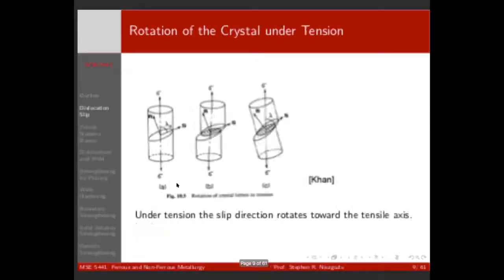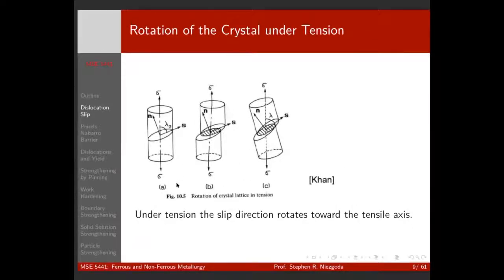So you may have seen this; it'll come up in the reading, but single crystals: if I cause slip here on this plane, and I have this set top sliding relative to this, I introduce a moment. So that leaves me a rotation of my sample. Because if we think about a tensile test, these grips are fixed.